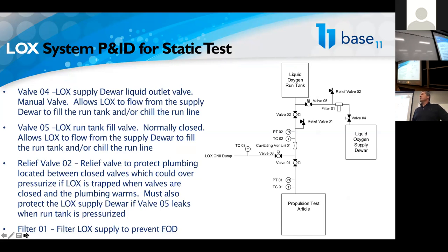And you wouldn't necessarily even have to do it with computer code logic. You could also have a pressure switch in your system that would not allow the electrical signal to reach valve 5 if the pressure switch was open because the pressure was above a certain threshold. So there's lots of engineering ways to approach these issues. The key is to identify them and then figure out how to mitigate them.